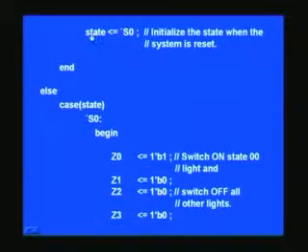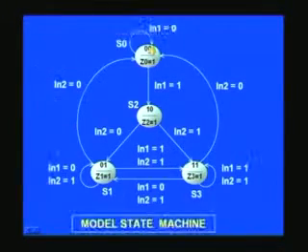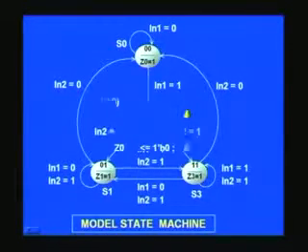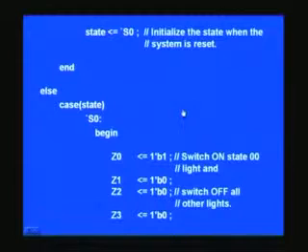And we have another variable called the state, which is the same as S0 mentioned earlier, or 0 0, that we have already seen here. So this is S0 or 0 0, right? That's what we are initializing here. In this initialization, once again note that this is a non-blocking statement. Always within the always block you have to use this, meaning it is equal to.